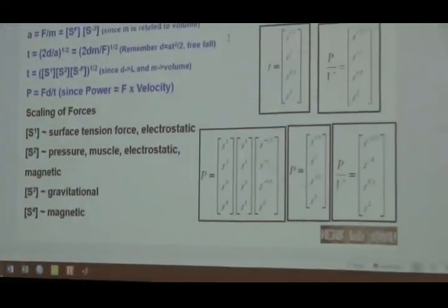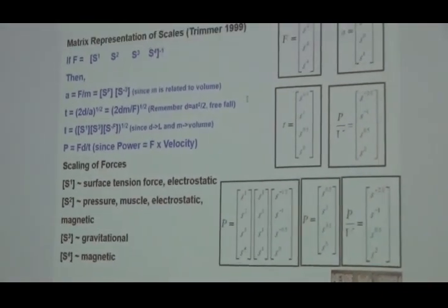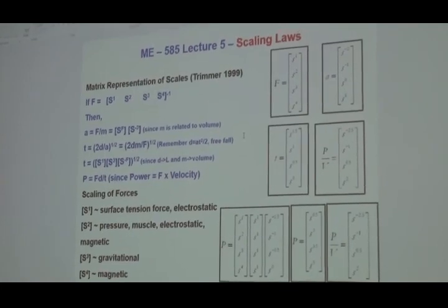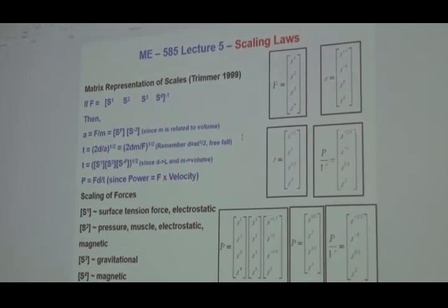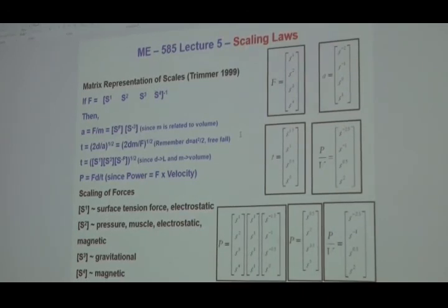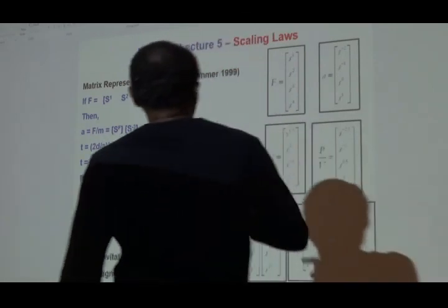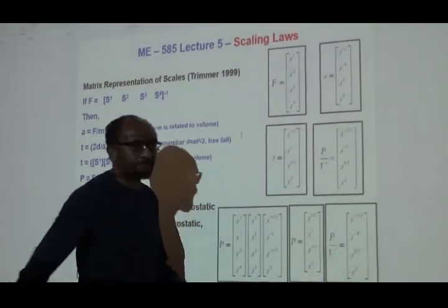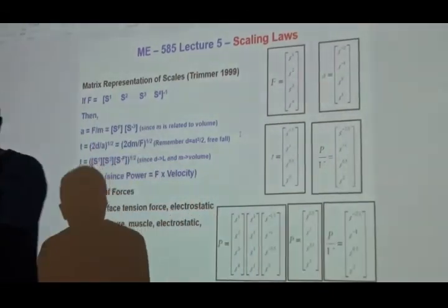So, what it says is, for a force which just scales with length, there are some forces which just scale with length. Okay? If you're pulling a string, it's a linear force. It's just going to scale with the length. There are forces that are applied on an area, like electrostatics. I'm going to show you that. Those scale with S squared. Now, if I have a force which scales just with the length, the power density scales with minus 2.5.